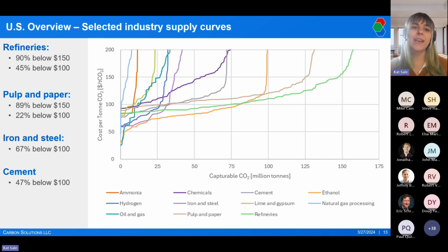So essentially, if you have a plant that operates at like 75% capacity, you would still want to size your equipment to be able to handle 100% of the possible CO2 generated by that plant. And other variations are from the baseline cost for equipment. On average, that cost is going to increase if you have a lower concentration of CO2 in a stream, i.e. that requires a higher energy investment in order to get a more pure stream of CO2.